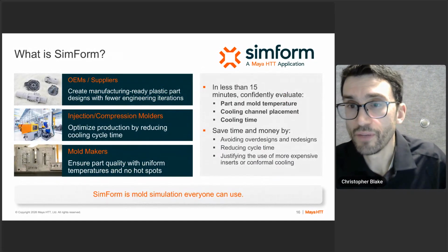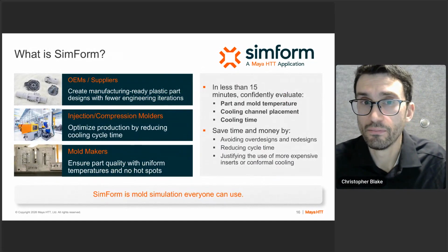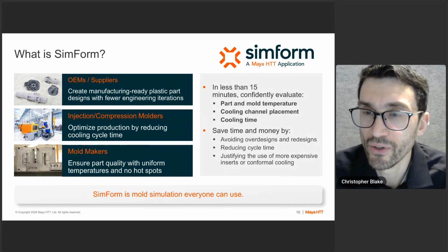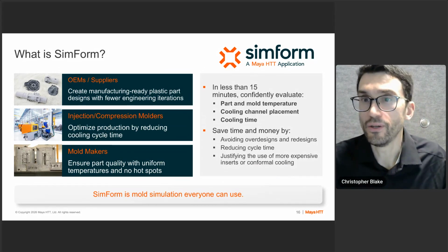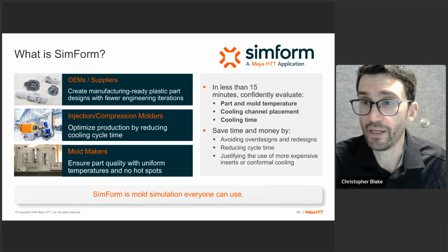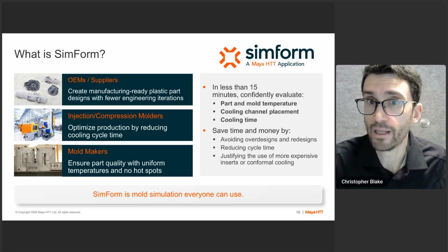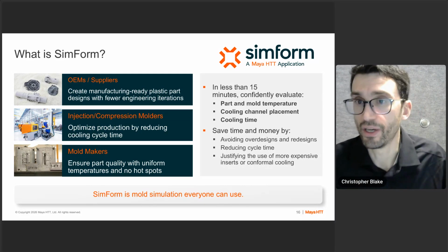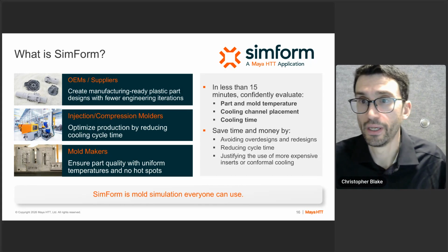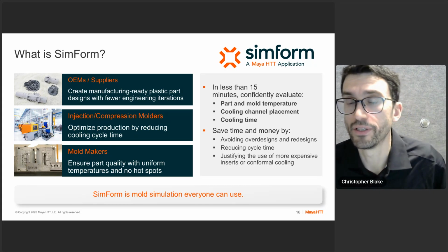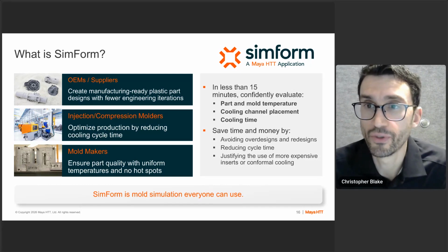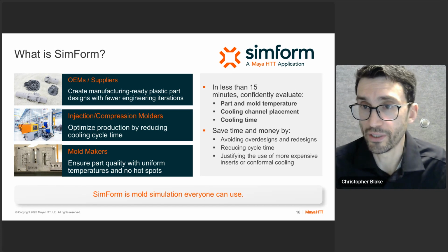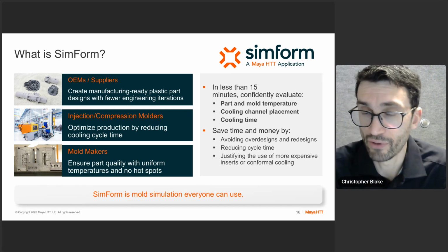So SimForm is our mold simulation tool. What we like to say is it's mold simulation that everyone can use. It's meant to be easy to use, and also used earlier in the design phase, in the preliminary design phase as well, because in less than 15 minutes, you can evaluate the temperatures on your plastic part and on your mold as they evolve in time to help inform your choice of where channels need to be placed, as well as get an estimate of the cooling time for the part, which is, as we know, a driver of cycle time.